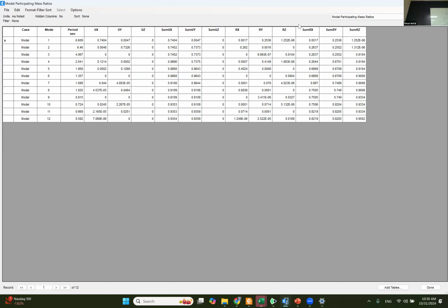Okay, so it shows you the mode shape. The standards are telling you that you need to account for mode shapes that can vibrate. Because let me tell you right now, when this equation was solved in the structure, it accounted for 12 mode shapes. Let's see, 12 mode shapes, how much mass they vibrated. It vibrated 93% of the mass. So that means there are some other modes still not accounted for that are needed to make this number 100%. So I would need to add more mode shapes, but the standards say enough is above 90%. If you were able to vibrate 90%, that's enough for me.